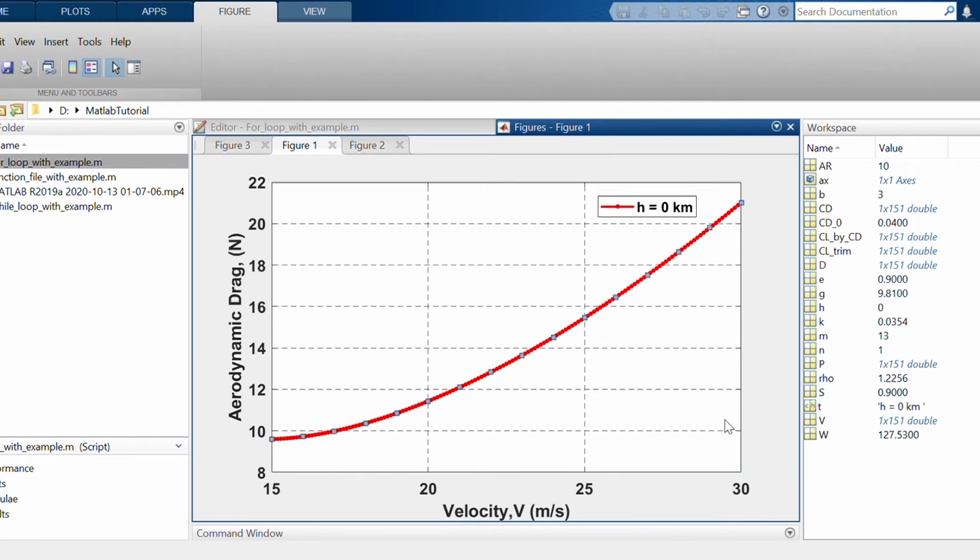So here you can see now it's a circle. Very fine, you just decrease the line width, go to marker, put the marker size 2 and the marker whatever you want. Currently it is a circle, just put a star and you will get a star. In this way you can modify your figure. Also some options are available if you go to Edit and Figure Properties.